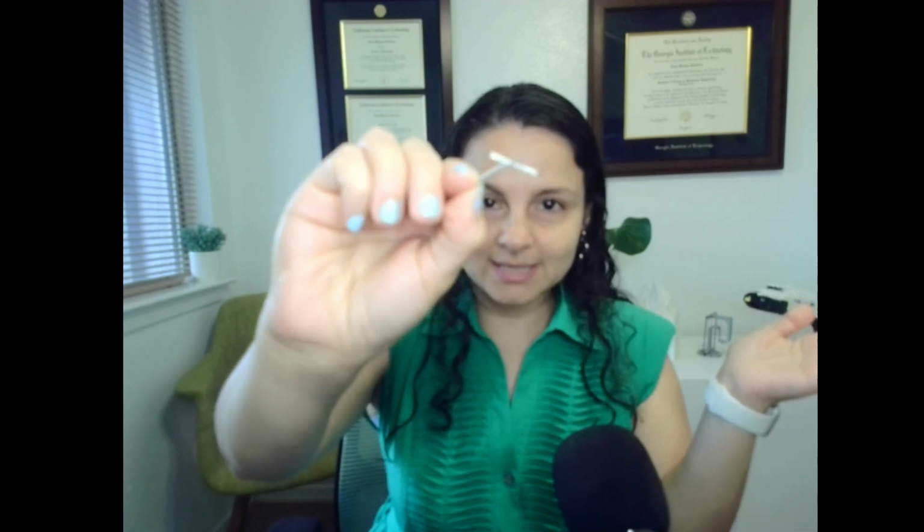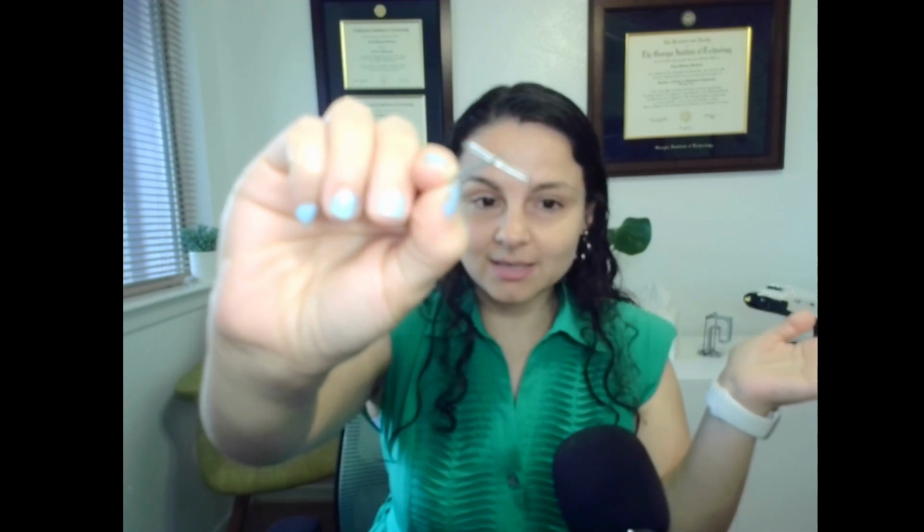Okay, so see that? It stretches, it gives. You can feel that there's some warning before it might eventually break. Let me see if I can get it to actually break. Actually, I can bend it all the way over and it still doesn't break. If I bent it back and forth a few times, it would. But that's a hallmark of ductile failure. We get permanent deformation before fracture.